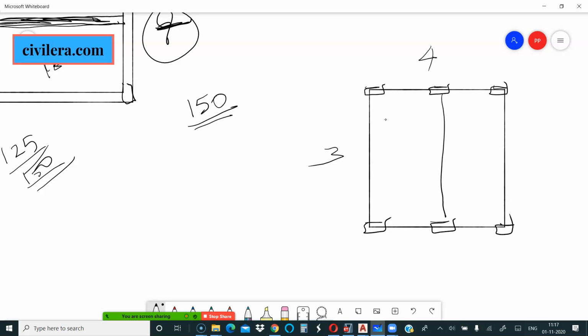I am not going in depth into that, but that is another need for having a beam, to tie the column. So at every level, your columns preferably should be tied by a beam, if not by a slab which has continuous steel over it, which is like a concealed beam. Let us not get deep into that now. Let me just tell you the need of a beam. The second requirement of a beam is to tie the columns.